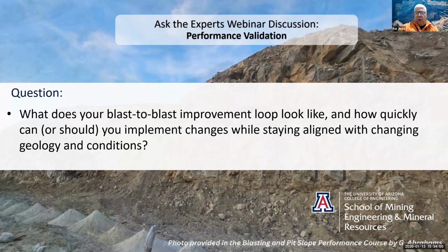After we mine off the trim, do we need to review the bench performance? Or we should review the bench performance. Did we achieve compliance to the design? Are the crests and toes in the right place? Did we achieve the bench face angle? Do we have effective catch bench width? Did we achieve the DAC for catch bench reliability, 80-20, 70-30, whatever your design acceptance criteria might be?